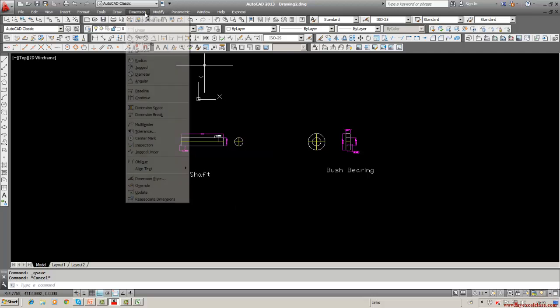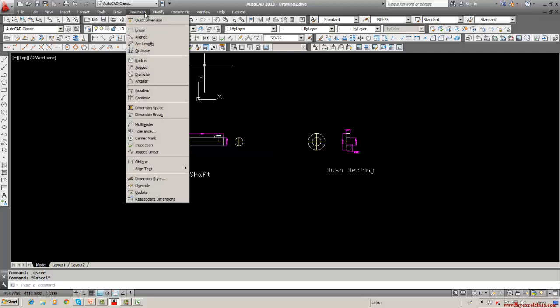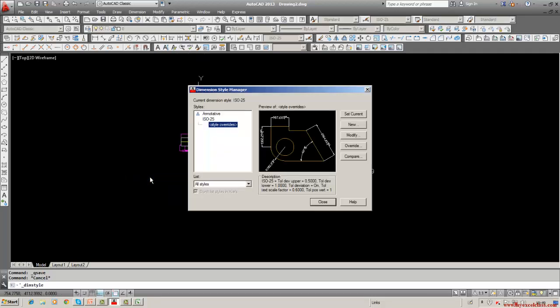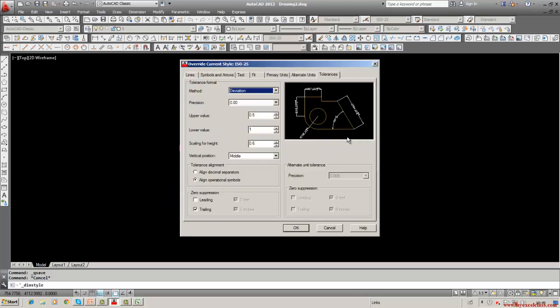Now, we have different methods of expressing the tolerances. We will see here. So now I have discussed the deviation, how much it deviates from the design side or nominal side, how much on the plus side, how much on the minus side. And there are different ways of expressing. Symmetrical, I told you, should be plus or minus equal on either side.